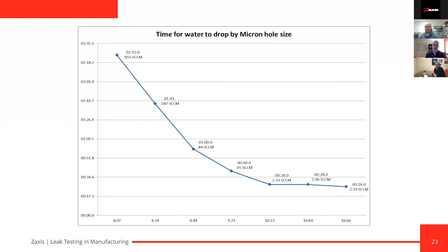Yeah, you'll want to make sure that when you vent the air out of the test part, it doesn't get into the tester. So if you have air that's going to get from the dirty part into the tester, you'll want to have a filter, or just vent the part externally on the fixture and not through the tester. So either a filter or just vent it externally from the tester would be my answer to that one, Tom.